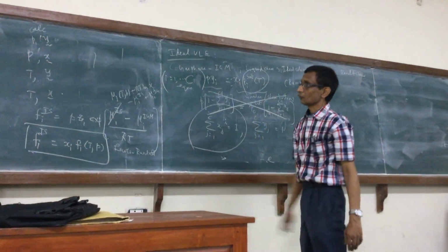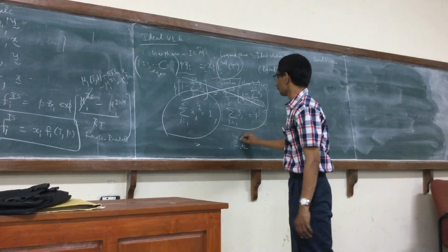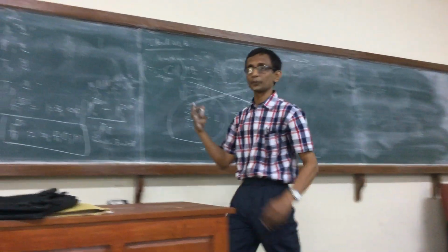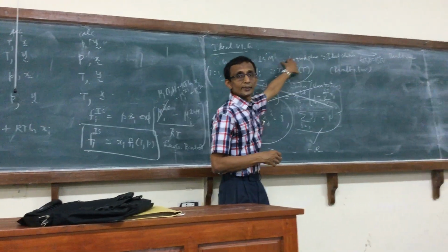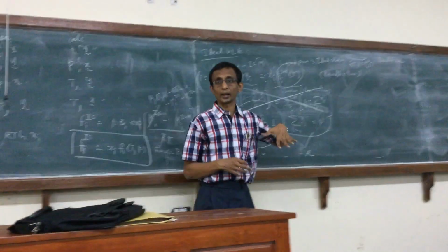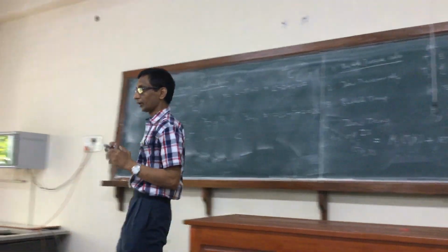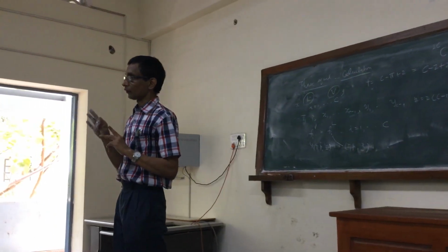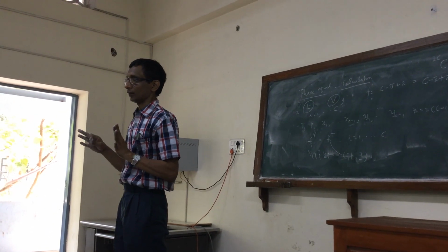So for instance, in the dew pressure calculation, you have to make sure that this equation is also satisfied, because sometimes the way the algorithm is written, you will directly be focusing on these and ignoring this for a while. But ultimately, you have to make sure that all the equations are satisfied. The mole fraction constraints will be an important part of the equations when you are calculating phase equilibria.